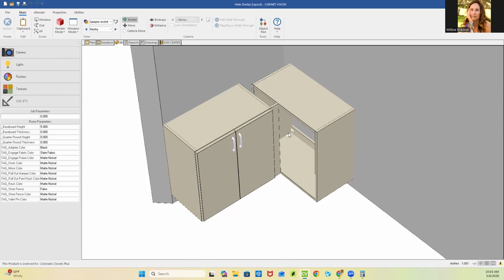In this case, 3 inches. So it kind of sets the standards. Exactly. And as we get into the actual corner cabinet, you'll see how where this filler connects dictates everything about how big the panel is here, where this vertical filler that the hinges are going to get attached to are. It's also helpful to have all of those dimensions dictated because when we get into manipulating partitions and other weird objects to make this all work, we're treading on the line where we're breaking the logic of the cabinet, and our connection systems will stop working. So we want to not have to manipulate dimensions that much, if that makes sense. Makes sense.